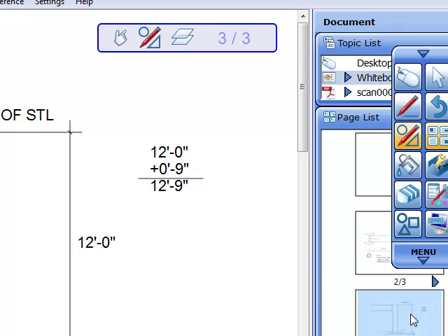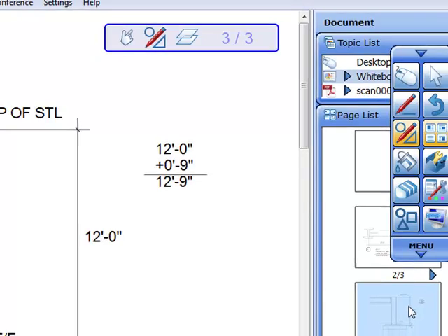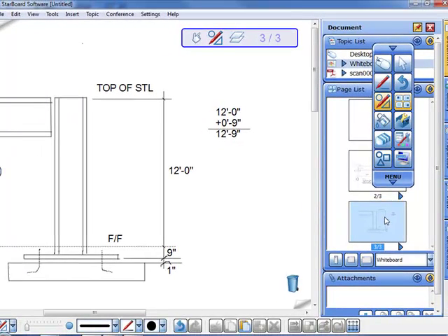Wouldn't you subtract the size of the base plate? If you submit this and they cut the I-beam at 12 feet 9 inches, your whole structure is going to be off by that half inch or whatever that base plate is. I see what you're saying, but they say it differently in the book, don't they? Because they say the floor line to the top of the steel plus the floor line to the bottom of the base plate equals the total height of the column.